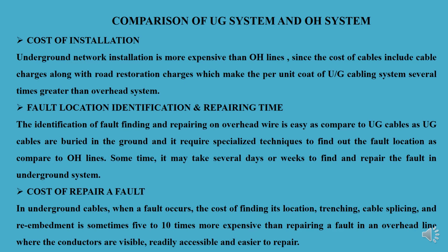Cost of repairing a fault: if any fault is there and you have to repair it, the repairing cost of this underground system is very expensive, right? We can consider it is 10 times more than the overhead network system, because of the trenches, the locations, and cable splicing and re-embedment, right? So for that purpose it requires more and more cost in case of an underground system.